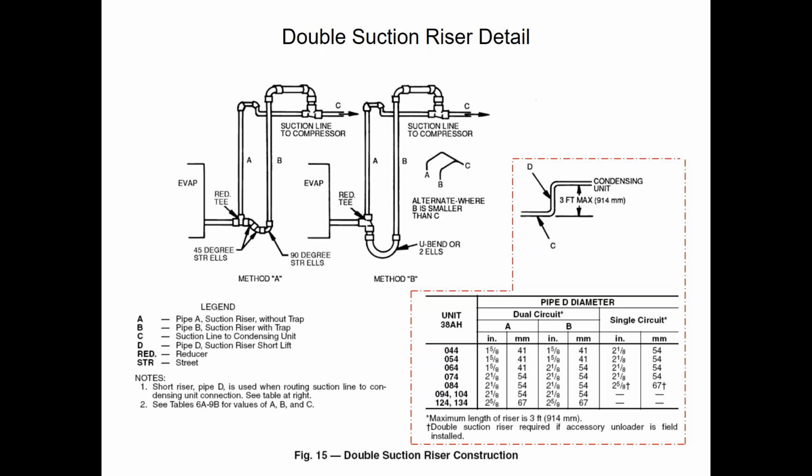Okay, it's not the gas, it's not the POE oil. It's simply the amount of oil that's in the new hermetic 410 scroll compressors. So make sure you always are using 1/2-inch tube evaporator coils. And again, it's all a velocity thing.